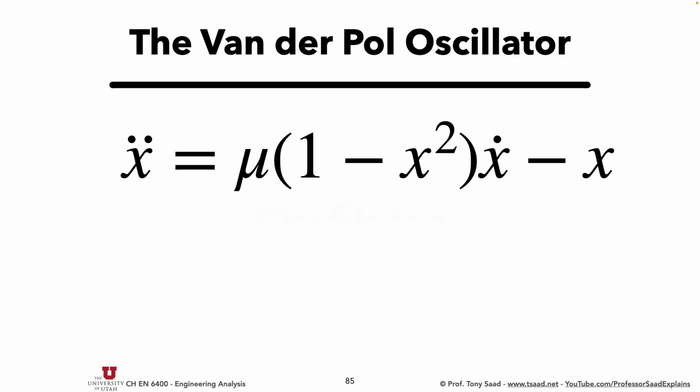This would be where you would have a kx, but anything that's multiplying a velocity, which is x dot here, is typically a damping term, like drag. So it's going to try to slow down the system from being extended or compressed. And this coefficient here is highly nonlinear because it depends on the position itself. There's a parabolic response on the position, x squared.